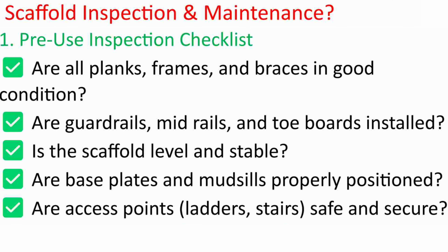1. Pre-use inspection checklist. Are all planks, frames, and braces in good condition? Are guardrails, mid-rails, and toe boards installed? Is the scaffold level and stable? Are base plates and mudsills properly positioned? Are access points, ladders, stairs, safe and secure?